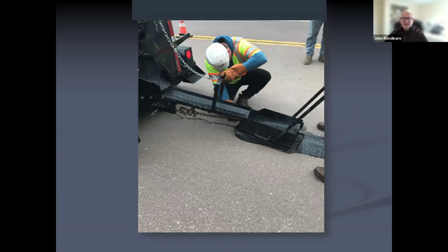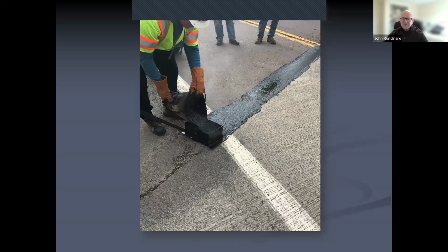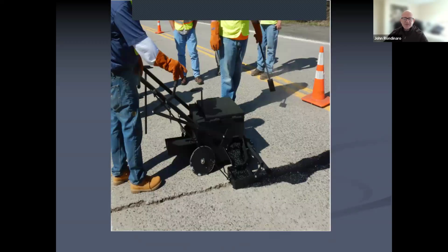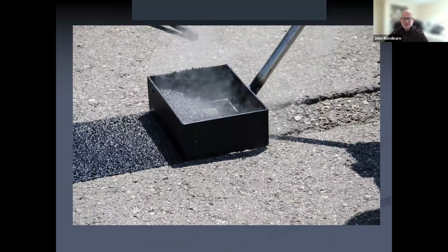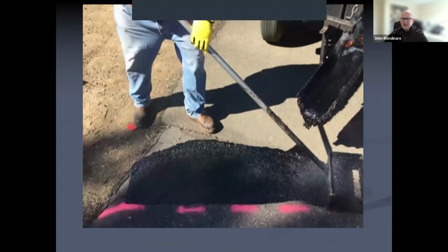It's really nifty. It's almost like a ready mix unit. The melter unit pours it out the back of the chute, and then you can put it into a drag box. All kinds of different ways you can convey it. You can carry it in a bucket to your drag box. You've got little buggies that you can use for your crack filling or crack sealing or mastic sealing activities. Drag box is typically a pretty standard way of doing it.